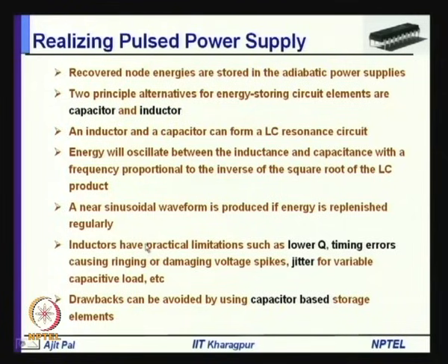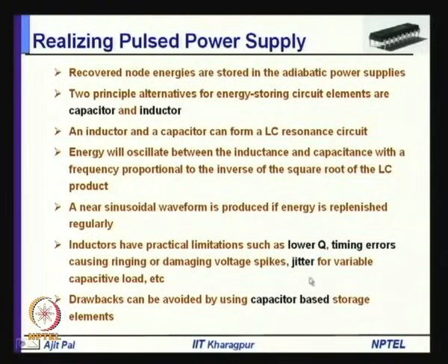But unfortunately, whenever you are going for VLSI, realization of an inductor is very difficult, particularly an inductor realized using a VLSI circuit on a chip will have a very low Q. The Q value is very low, and there are many limitations like lower Q, timing errors causing ringing or damaging voltage spikes, jitter, and variable capacitance loss, and that is the reason why, instead of using an inductor, capacitor based storage elements are normally used in realizing